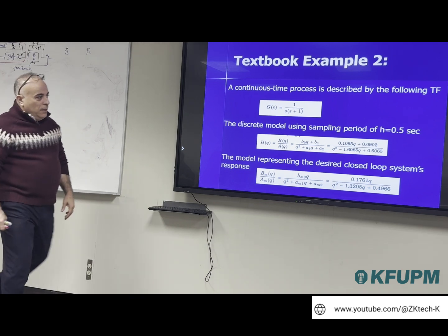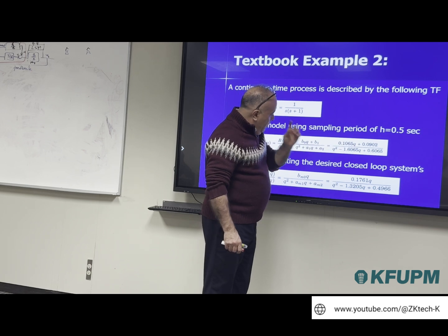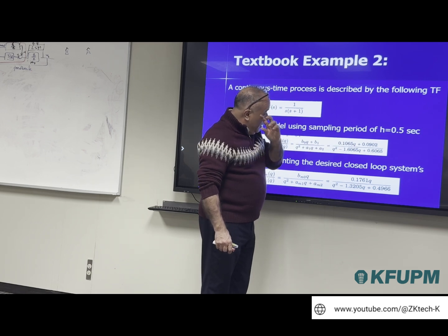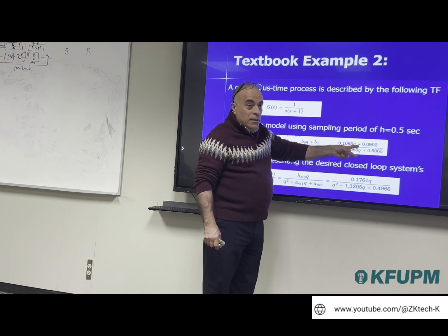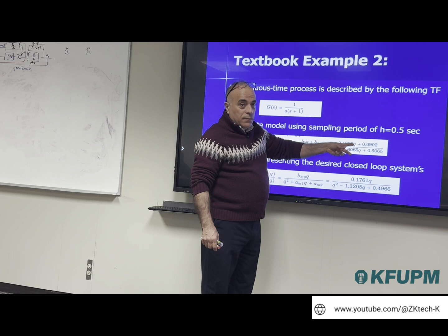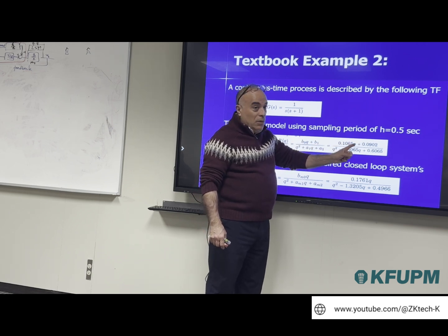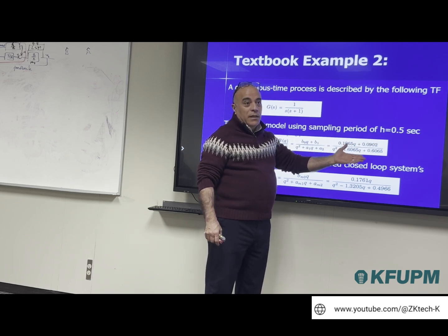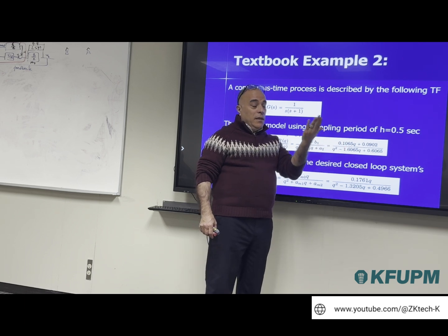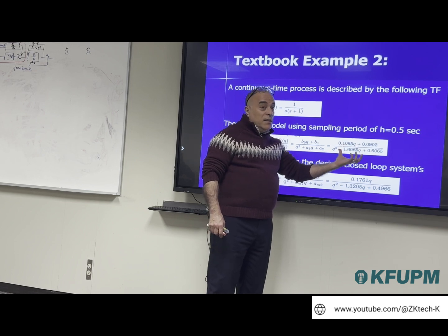The second point, we look at the system here, and when we solve for the system, I will show you later in the slides, we have a zero that is finite, but the zero is negative. Right? So we put here q, this one equal to 0. q is equal to minus this element divided by 0.165, so it's negative. There is no minimum phase problem or something.